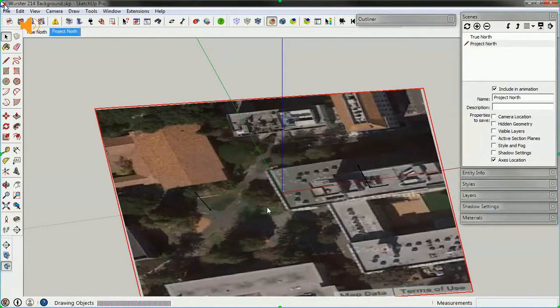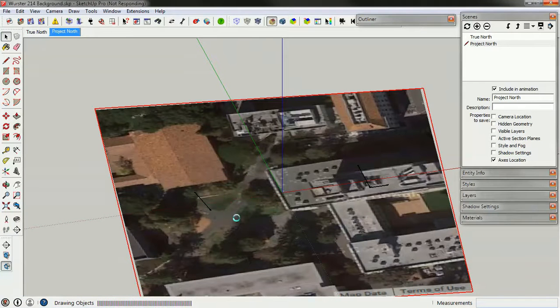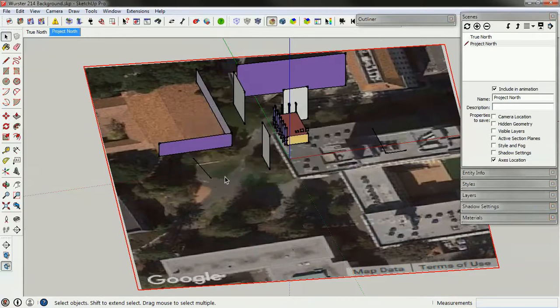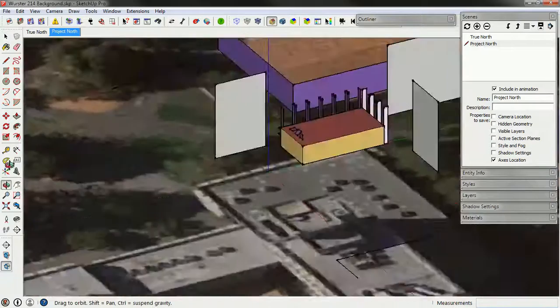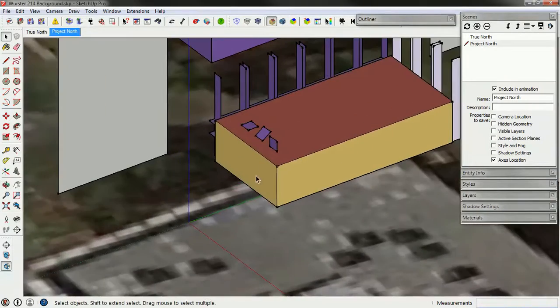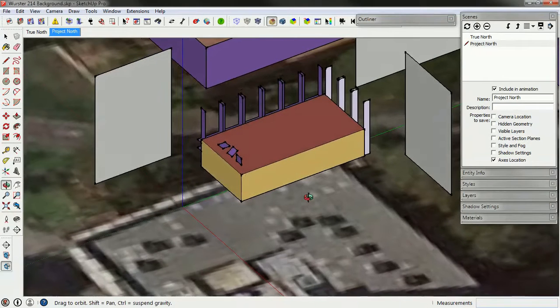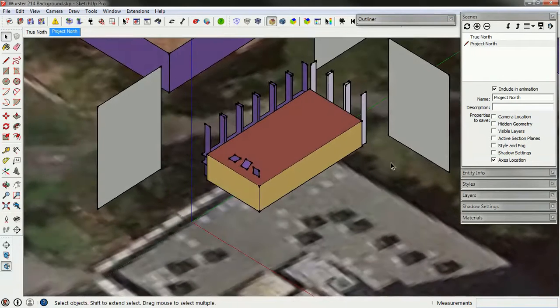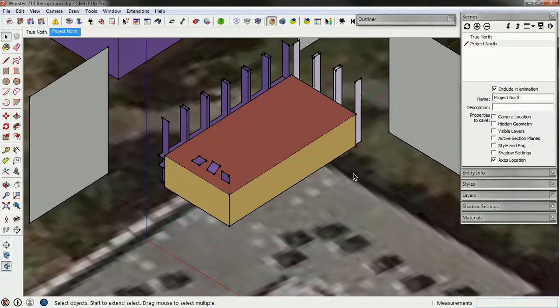Okay, we are pretty much done with this tutorial. There's a few other things I want to go over relative to your geometry inputs for EnergyPlus. So here's a few tips that will help you out as you model your own zone. There are some rules that EnergyPlus has in terms of the way that it reads the surfaces. So I want to show you some tricks. The first rule is that there cannot be L-shaped or U-shaped surfaces in EnergyPlus. It doesn't know how to read them. It also can't have curved surfaces. So there's a few ways of getting around this.